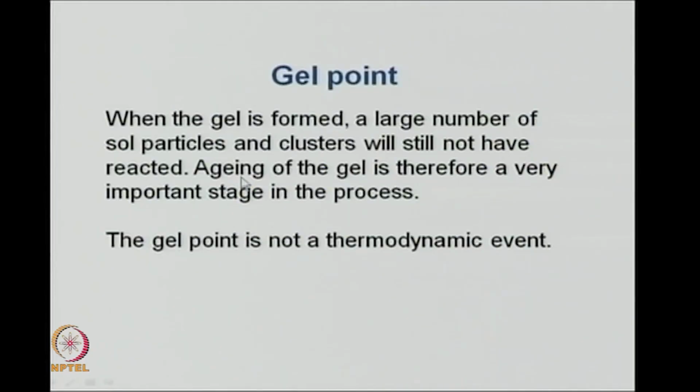So, the entire gel has to get connected. The gel point is the point where you form a single interconnect, that is all through the liquid you have one interconnect, but that does not mean that all the particles have hydrolyzed. There are still particles which need to be hydrolyzed, and so you need to do aging.